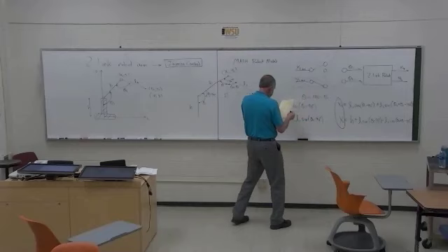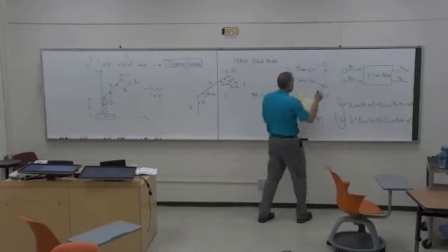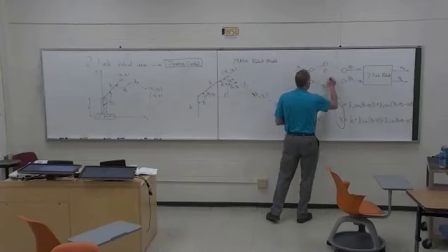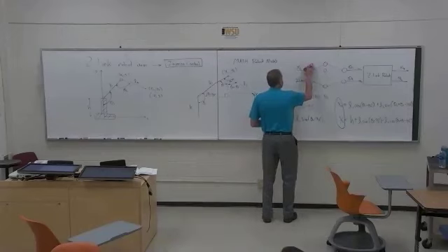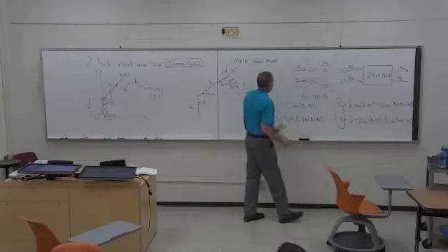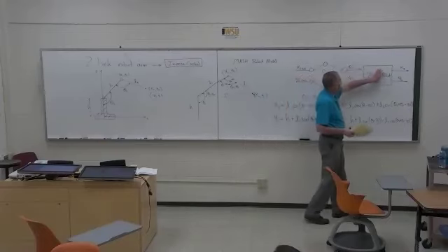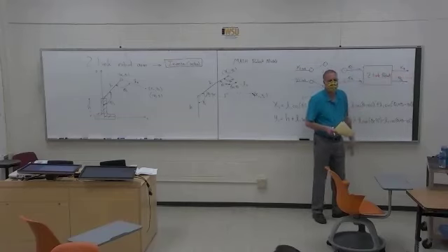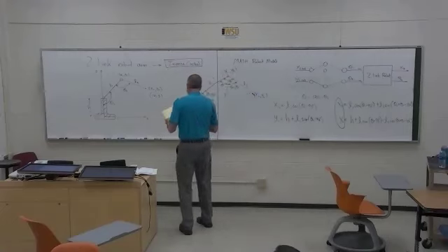To specify a desired value. This is what we want. You can call it desired or a reference. Let's call it a reference. That's probably more technical. So we put in where we want the end effector to be. The controller is going to figure out what the thetas need to be so that when you put those thetas in, the robot goes to the spot we want. And that is inverse control.